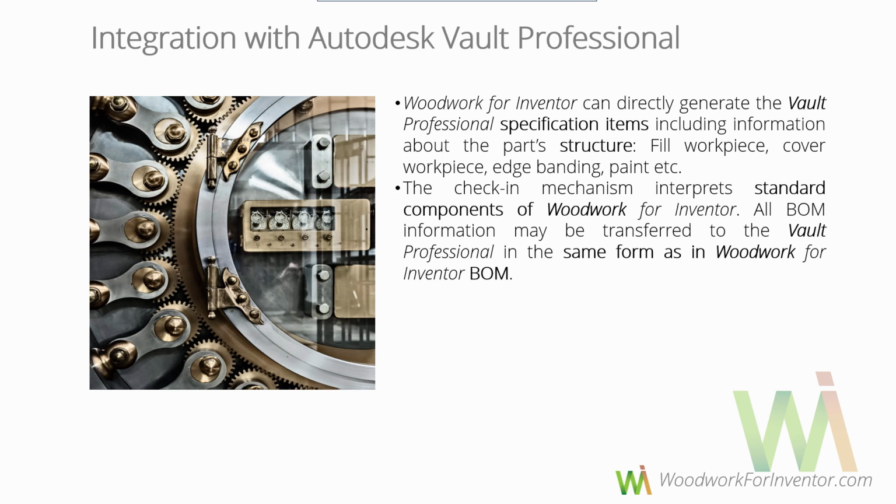So the check-in mechanism interprets standard components of Woodwork for Inventor. What does it mean? Our standard components such as handles, hinges, minifixes, confirmats, etc. In most cases, they are designed as one single part, maybe with the exception of the hinges, which are designed as assemblies. But most of the standard components of Woodwork for Inventor are designed as standard iParts.